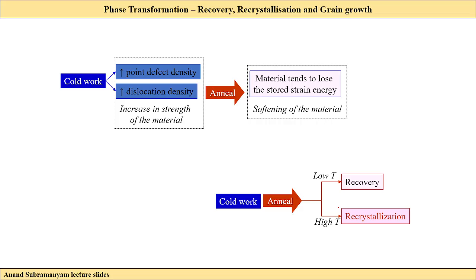So it will oppose whatever dislocations are coming from inside the grain to the grain boundary, right? Because the dislocation starts piling up at the grain boundary, and they cannot move, right? Dislocations have their own strain fields, so they will try to repel each other, one dislocation from another. So they will try to maintain a gap because they cannot coalesce, because they have strain fields around them, just like magnets. The north poles cannot coalesce because of the magnetic field around them. So the dislocations cannot coalesce, and they will try to repel each other because of the strain fields.